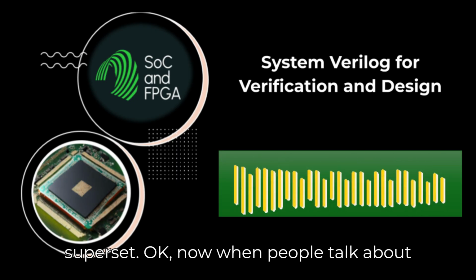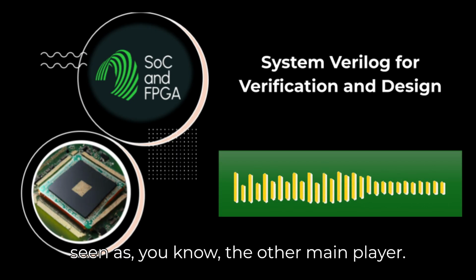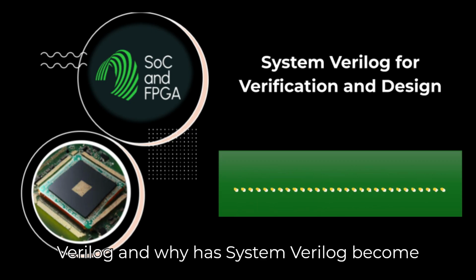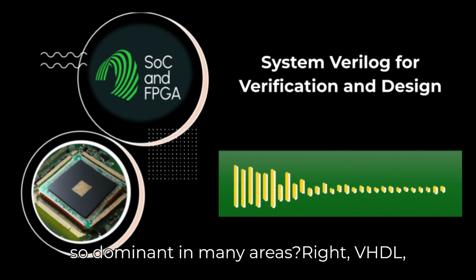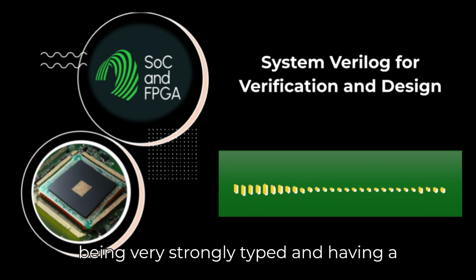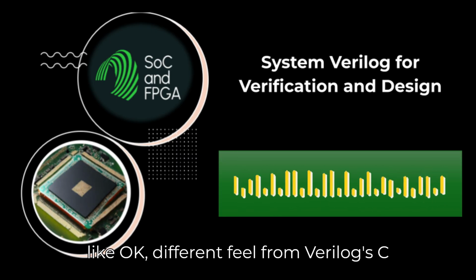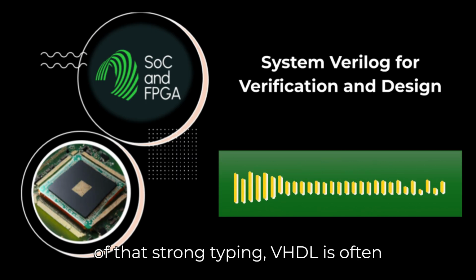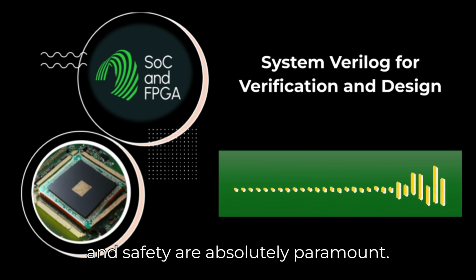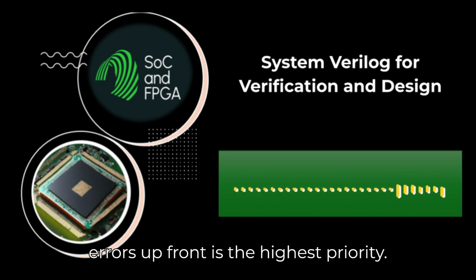Okay. Now, when people talk about hardware description languages, another big name always comes up, VHDL, often seen as the other main player. How do they stack up against SystemVerilog, and why has SystemVerilog become so dominant in many areas? Right, VHDL. That's the Very High-Speed Integrated Circuit Hardware Description Language. It is definitely prominent. It's known for being very strongly typed and having a more verbose Ada-like syntax. Ada-like, okay. Different feel from Verilog's C-like style. Very different. And because of that strong typing, VHDL is often preferred for designs where reliability and safety are absolutely paramount. Think aerospace, maybe automotive applications, places where preventing errors up front is the highest priority.